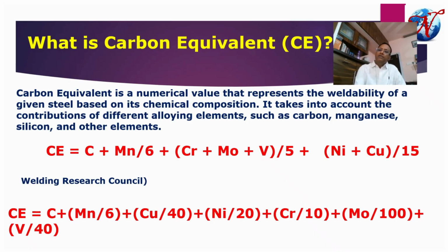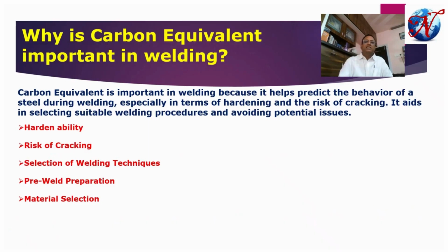According to the carbon equivalency value, it is determined what the weldability of your inspection material, your weldable material, is. The lesser the carbon equivalence value, the better. When the value of the carbon equivalence is very, very low, then we can say it's a weldable material. That means the welding can be carried out in a very controlled manner.